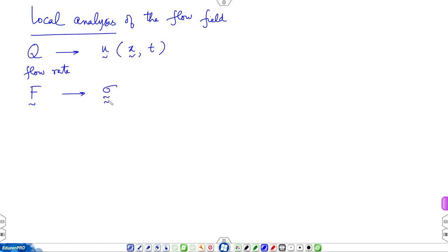are expressed in terms of stress. You remember that stress is force per unit area, but force is a vector, area is a vector. That makes sigma dependent on 2 directions. One is the direction of the force, the other is the direction of the area vector.